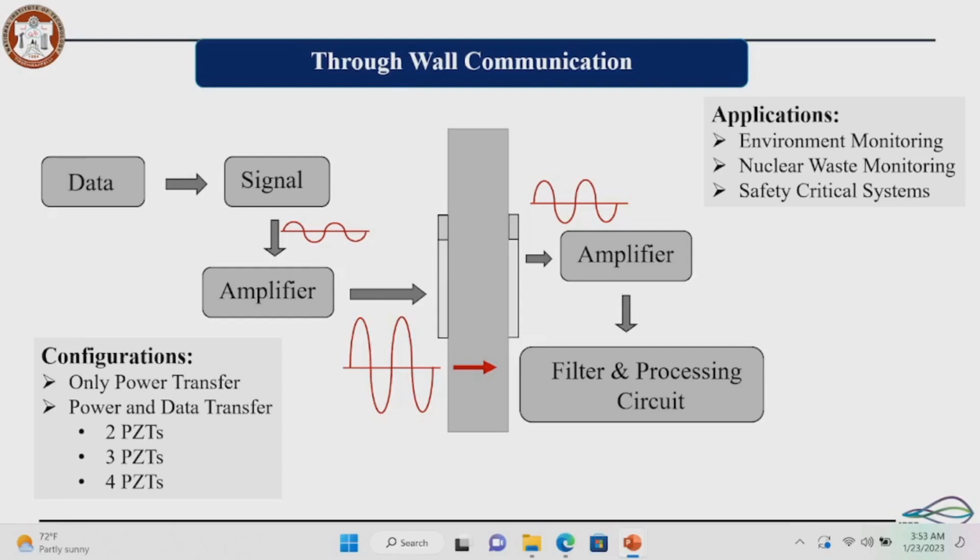If we talk about the hardware, we will have 2, 3, or 4 piezoelectric patches, depending on the application. With 2 piezos, one will be the transmitter and one the receiver. With 3, the power and the data can be transmitted, but one by one, not simultaneously. When power is transmitting, one piezo takes the power and charges the inside battery. The second piezo is responsible for the data transfer. Once the battery is charged, it will start the data.